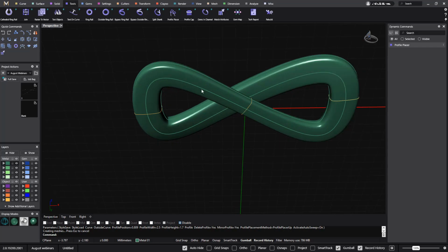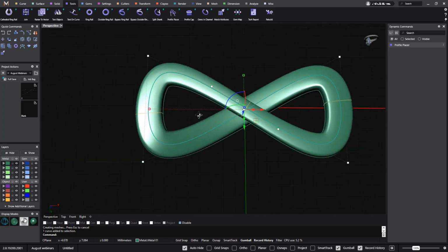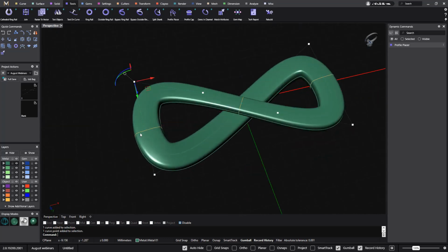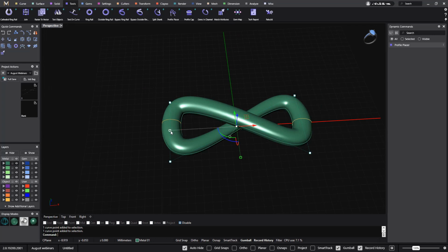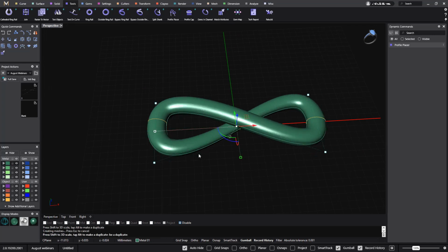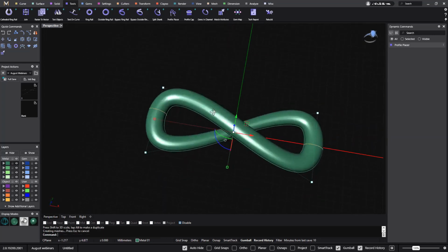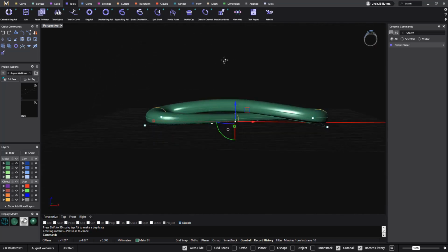So of course we can keep playing with the curve. All right. So I go to curve, my control points get in the viewport, and what I will do, because I feel like this part here is too flat, I want it roundish because it will look nicer. So what I can do is select just these 4 points, and now what I will do is move them a bit up. All right, so now I think that the shape is nicer.